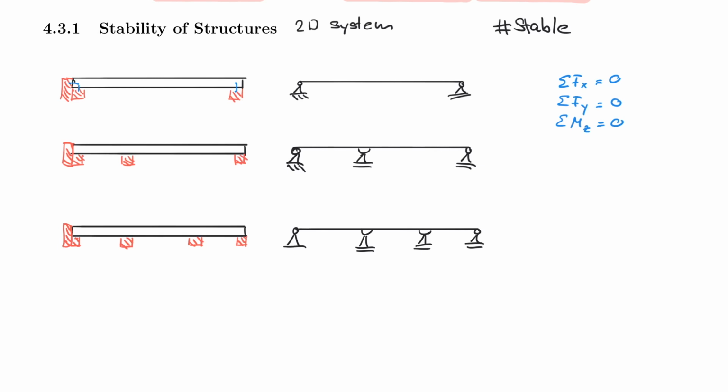If you want to think about this from a standpoint of deflection, you probably understand that this system here deflects the most if you put a force on it. So let's actually pretend we have a force sitting somewhere on there. So this force, of course, would deflect this system very differently than this system, for example, or this system. So this would just start to bow down, whereas this one here would bow down here, and then here you would actually have an uplift, if you will, or like an upwards bending. We talk about bending much later, but you understand that this support here changes how this entire structural system responds.